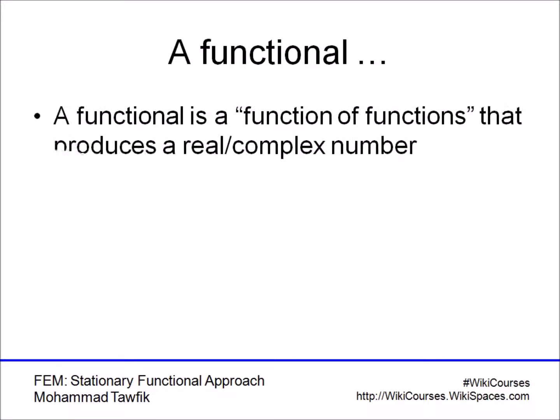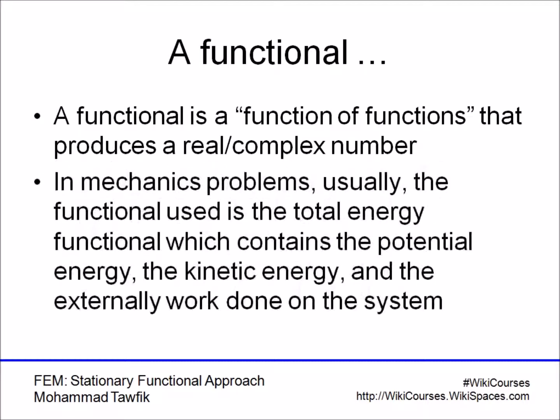What is a functional? A functional can be defined very simply as a function of functions. This function of functions in mechanics problems is usually the total energy functional. If you remember, the total energy in mechanics contains the potential energy and the kinetic energy.